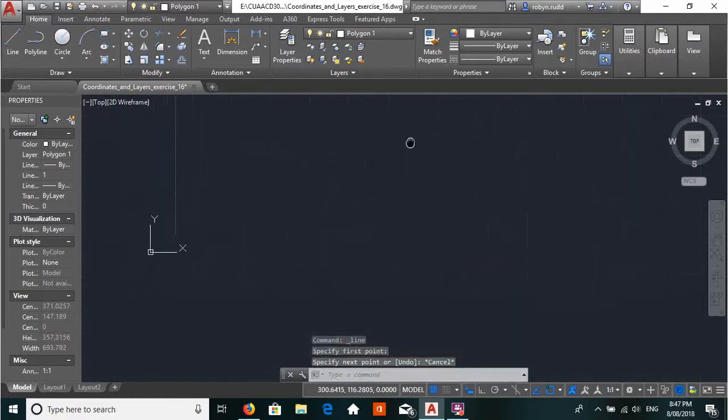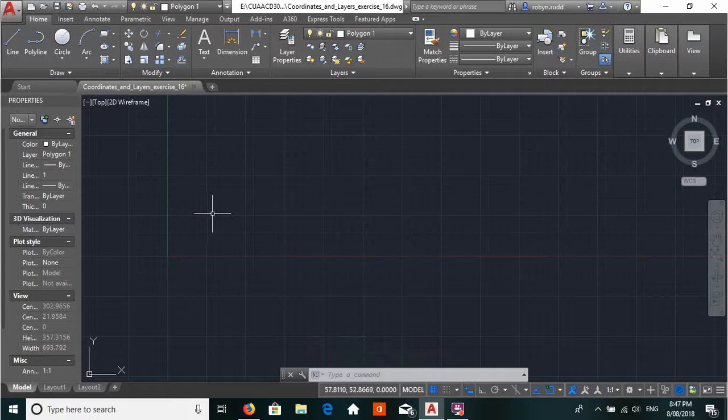But just to keep in line with what they're asking, they want you to start with an absolute coordinate, so it's a starting point, at the coordinates 73 in the x-axis and 38 in the y. That means that from 0,0, it is 73 going to your right, and then up in the y direction, because it's positive, being 38.